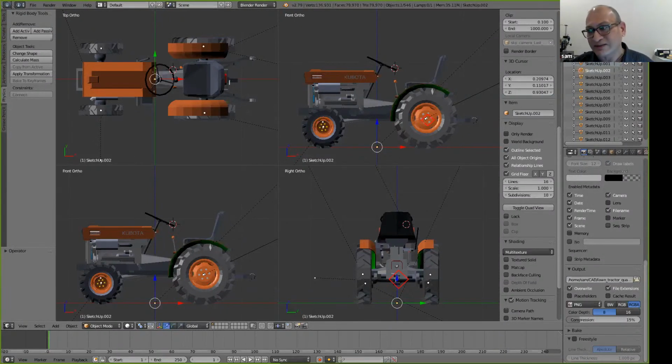Now, base link is supposed to represent the whole vehicle, for example. In this case, we have to deal with what we have over here. We have this CAD, and it's exactly located at your X, Y, and Z 0s right in the center, as you can see. When I define my link, I want to put my base link right at the point on this tractor where it sits at the rear axle in the center, right? Okay, so that's our challenge.